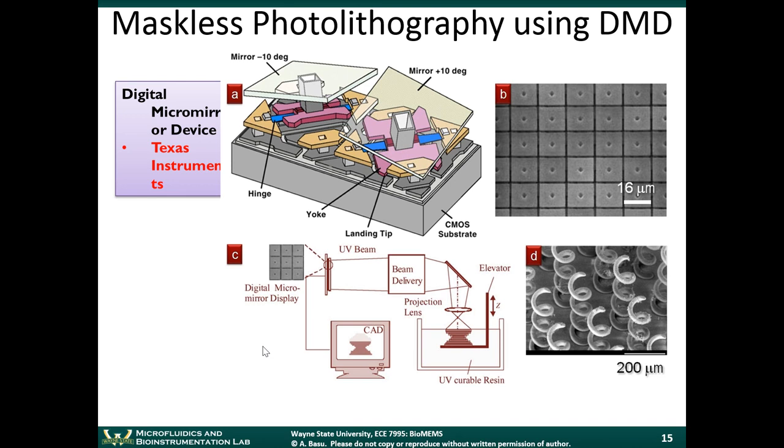In fact, this projector here is not using a micromirror device. It uses a 3-LCD panel, but a lot of projectors are DLP projectors. The ones that you see in the movie theaters are often made of micromirror arrays. It turns out that these DMDs can project light patterns. They're very good at projecting light patterns. So why not use them for lithography? This has turned out to be a pretty successful idea.